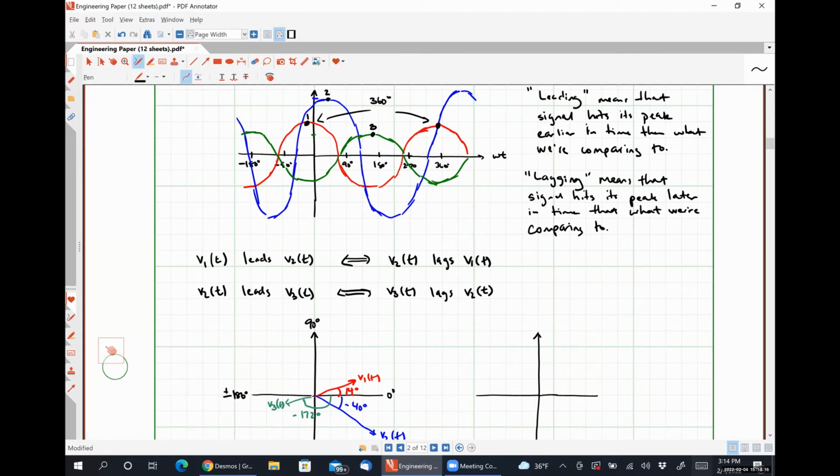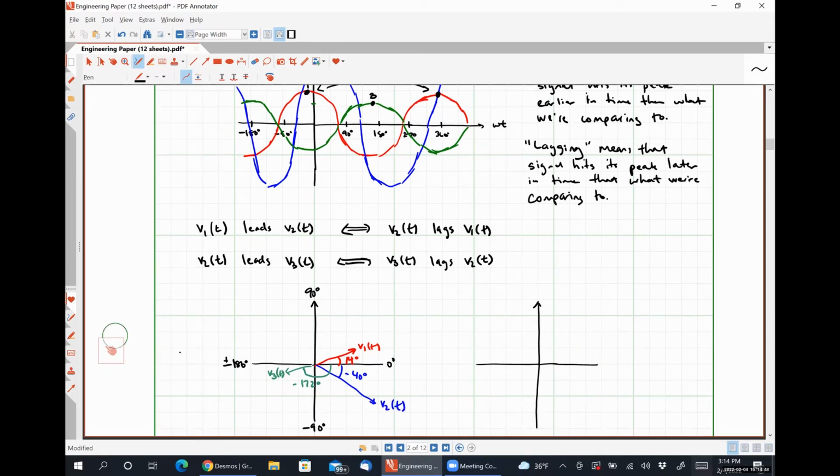So you're looking more at the phase diagram to see which one leads and lags, rather than the graph up top? Yes. Thank you. No problem at all. The top diagram, there's nothing particularly wrong with it. You can tell leading and lagging by effectively picking the two peaks that are closest together, and then whichever one comes first is leading, and whichever one comes second is lagging. But to me, the phase diagram representation, which is what we're going through right now, contains a lot more information, and it's much easier to interpret.